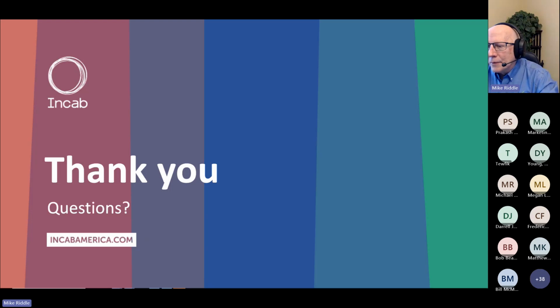Thank you all for the positive feedback. Oh, that's a good idea, Joe. I see your comment. Suggest you show 4 or 5 transmission spans and the errors on the same slides as the distribution spans. That's not a bad idea. Yeah, I'll have to look at that to illustrate that when the spans are short, you get an acceptable error level. Remember, I showed there like a 1% difference between average and ruling span calculation. But really, that's not the whole story there. Average span in that context doesn't really mean anything.